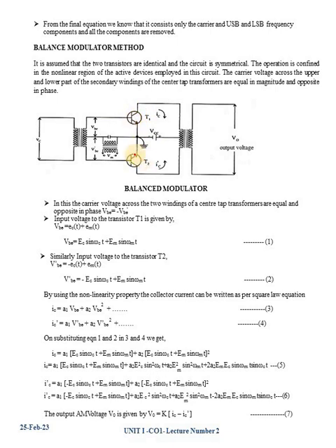and starts conducting. During the same time, the second half is receiving the negative half cycle, so it is reverse biased and there is no current flow in this direction. For a negative half cycle, the upper half of the circuit operates in reverse bias mode and this one operates in forward bias mode. So the current starts flowing from this direction, which opposes the upper half cycle.